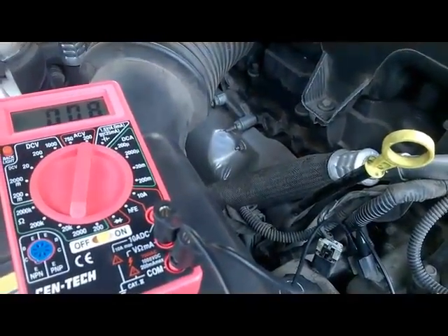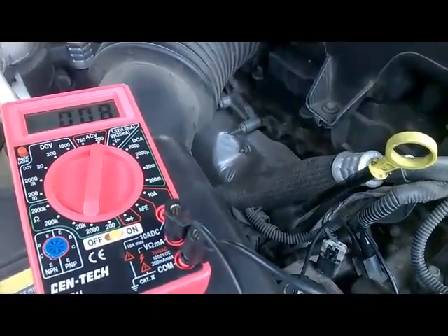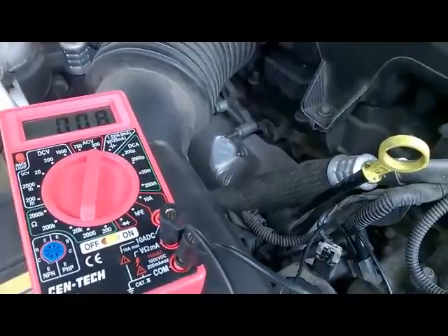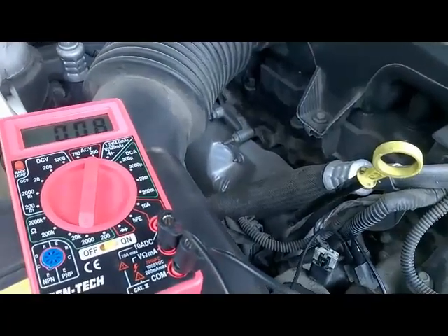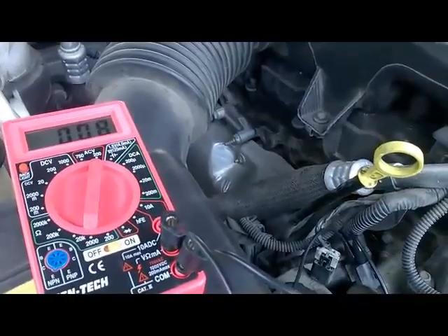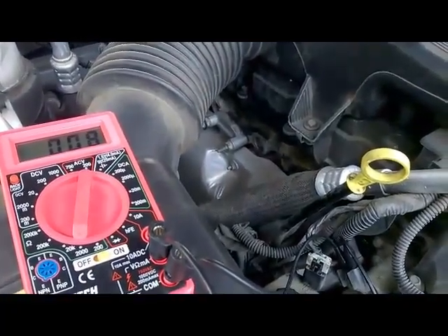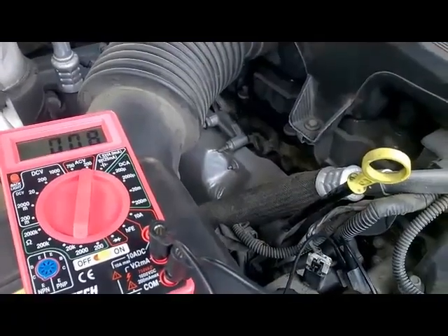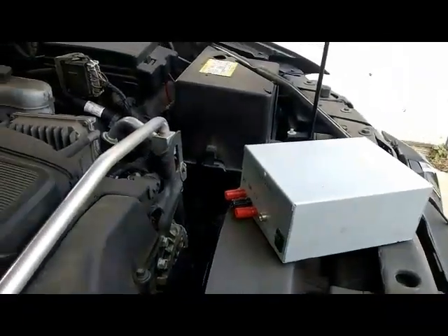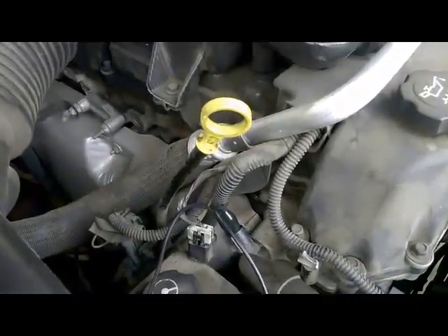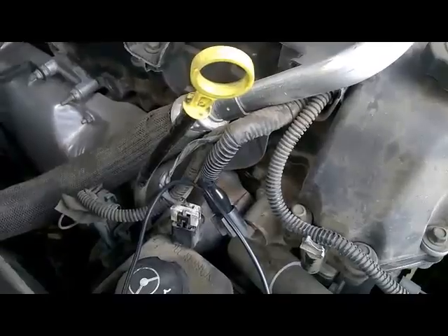I guess the only way to confirm more is to be able to do some bidirectional control to see if this solenoid is able to perform its functions. But unfortunately, both of my scan tools do not give me the capability to do bidirectional control on this cam actuator solenoid. So in other words, I'm going to have to do it manually by using a 12 volt power supply, and I'm going to manually energize the solenoid and see if it's clicking. I will do it with the engine off and with the engine running, and see what happens, guys.